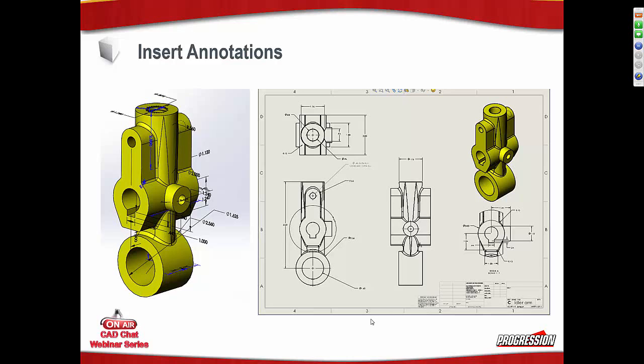Advantages of inserting annotations is that you can actually change the model directly off the drawing. You can just insert the model annotations or insert the model dimensions and then click on the text of the dimension, double click on it, and it brings up the edit box just like it does in the model file, and you can then change that value. Now the reference dimensions themselves, if you just insert a dimension or add a dimension to the drawing, that's not driving the model, but if the model changes, that dimension will change, so you don't have to worry about that.